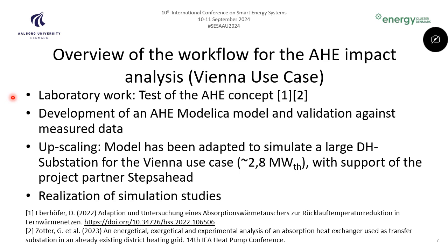From my side, there is the development of an absorption heat exchanger Modelica model, which I validated against measured data. And then we upscaled this model to represent a substation of the typical size in Vienna, which in this case was almost 3 megawatts. I did so with the support of the project partner Steps Ahead. And finally, we carried out different simulation studies for different scenarios to assess the impact of the absorption heat exchanger.